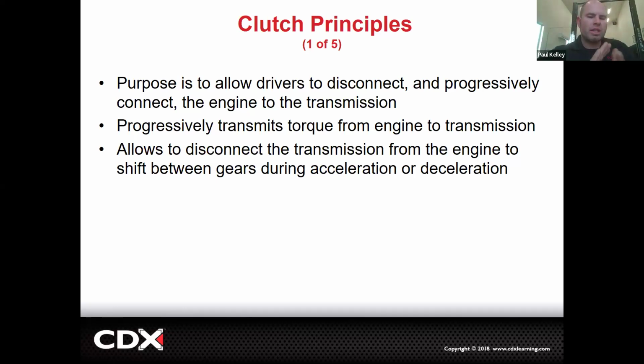By default, the clutch is engaged, so the release system releases the clutch, right? So as soon as we start having a problem like the clutch not releasing all the way, we want to look into the release system. That's exactly what I've got with this one. I push the clutch pedal all the way down, and it still grinds a little bit going into reverse. And you can tell the very first part of the clutch pedal just feels a little loose. I attribute that to air being in there. The reason I'd say that is because it was good until I opened up the bleeder and got new brake fluid in there. So somehow I got air in there.